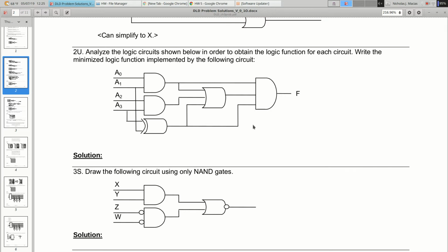And anytime you have a circuit and you're trying to write a truth table, my recommendation is put down labels at intermediate points on your circuit. Don't try to just write a table with your inputs and then list the value of f, because there's so many chances to make mistakes. Right? You got 16 values of f to fill in, and for each of those you have to calculate 3 values on the left, and you have to OR 3 of those together to get the medium value, and then you have to AND all of that. So do it methodically. Make yourself a truth table. And let me copy the circuit down here, or at least part of it.